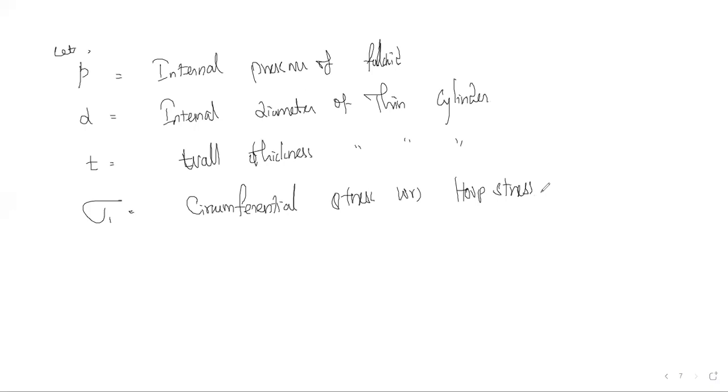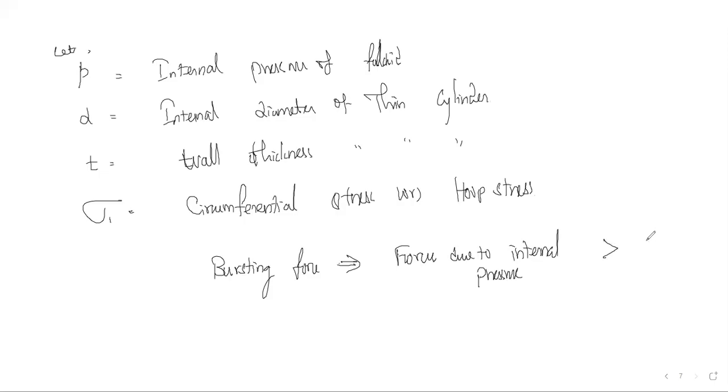Now the bursting force will take place if the force due to fluid pressure is more than the resisting force due to the circumferential stress.